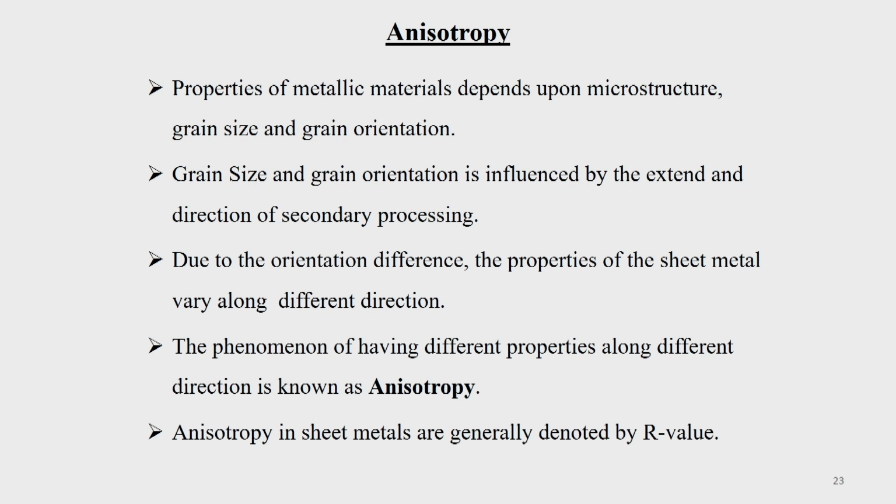A phenomenon which people abundantly use now is the texture. In most cases, after a large amount of deformation, you will find that the crystallographic planes of one grain are arranged along a particular direction. Similarly, you will find that for most of the grains, they are arranged along that particular direction. So, that is called the preferred orientation. After this extensive deformation, the grains will orient in a particular fashion, in a particular direction, which you call preferred orientation. Okay.